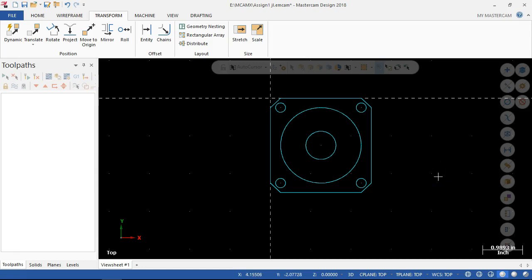If we're making 10, then I can stand at the saw. If I'm paying the material supplier 50 cents to $1 a cut, maybe I tell him to make 3 less cuts or 2 less cuts per 3 parts, and we go ahead and bulk up the machining. So juggling that information, and whether, like I said, you're having that conversation with yourself or you're sitting down with the machine shop manager, the purchasing manager, and saying, what do we want to do? Be prepared with that conversation.